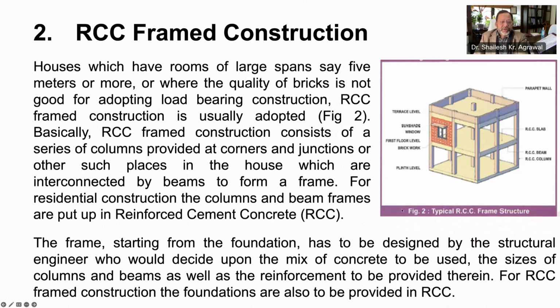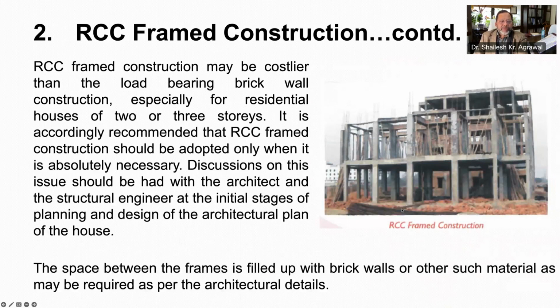RCC construction may be costlier than your load bearing wall construction, especially for residential houses of 2 to 3 stories. However, it is again the call of the owner, architect, and structural engineer to plan, design, and construct the house as per your requirement and budget. My advice is to go for load bearing construction up to 2 to 3 stories if good quality bricks are available in the region.